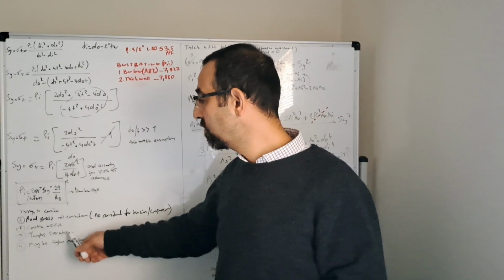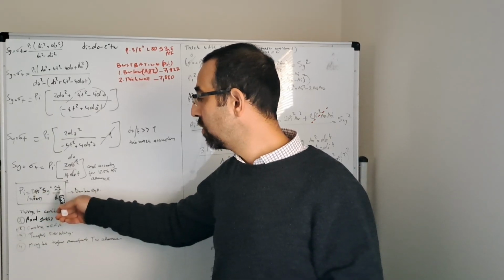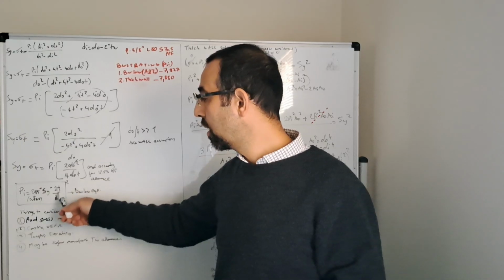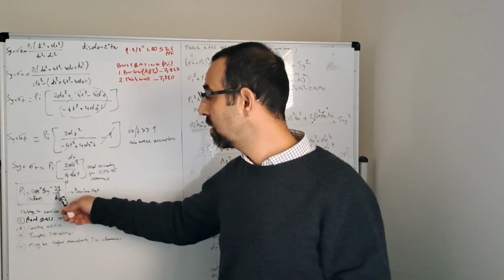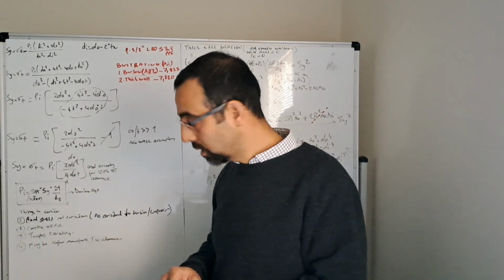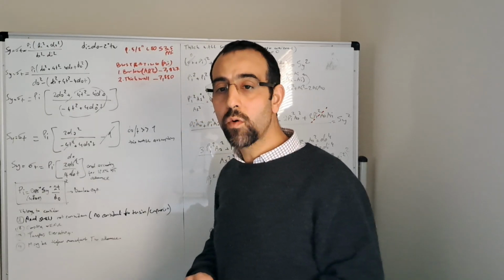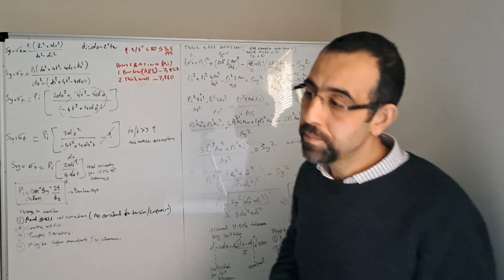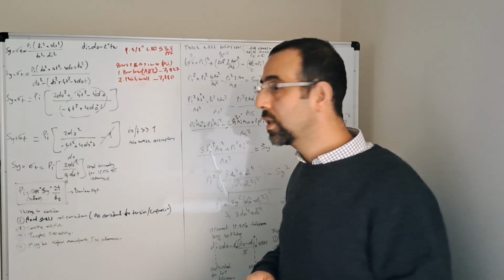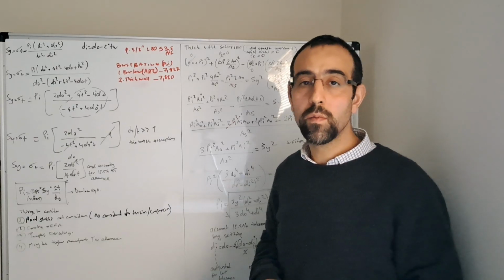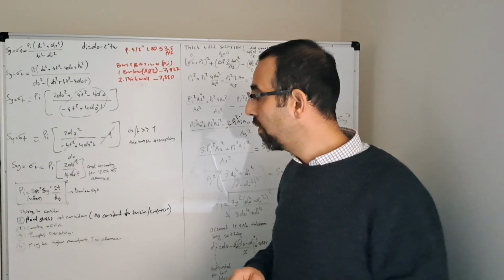Another thing to consider during the life of the well is that we do the workovers and then we rotate the pipe across the tool joints across the casing. We don't know the casing wear usually. It's very hard to quantify, and also depending on the production, tubing leak, etc., casing could be exposed to hydrocarbons, which we don't want.